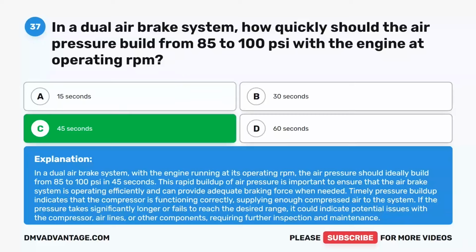This rapid buildup of air pressure is important to ensure that the air brake system is operating efficiently and can provide adequate braking force when needed. Timely pressure buildup indicates that the compressor is functioning correctly, supplying enough compressed air to the system. If the pressure takes significantly longer or fails to reach the desired range, it could indicate potential issues with the compressor, airlines, or other components, requiring further inspection and maintenance.